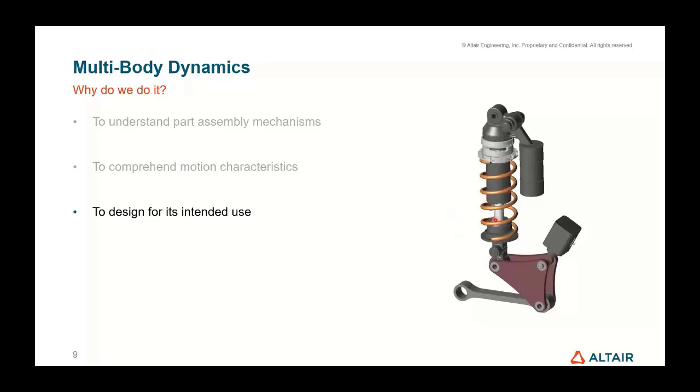And the moment where we start looking at spring damper systems as well, this is where we can link it up into Activate, and we can then simulate and understand the feedback loops and the response loops to understand whether we need to put more damping, less damping, more stiffness, or less stiffness with it too.